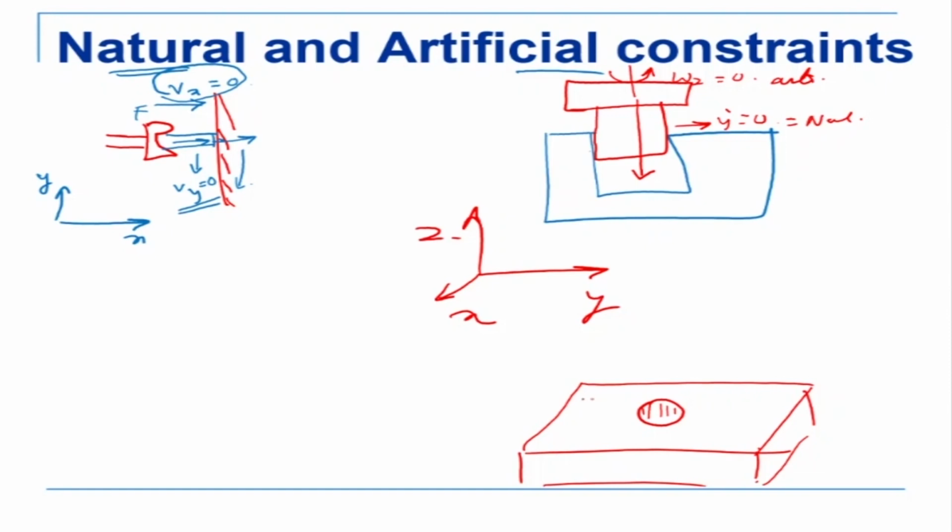So when the peg is here, if you can imagine that, let's say this is my peg, and I want to insert this into that hole. So the robot is holding this peg, and what it can do is it can try and approach the hole. So it has to have a velocity in that direction. Here it cannot force it down. So Fz must be equal to 0 because it can't force it through here. Sorry, Fz will not be 0, but the velocity in this direction, so Vz will be equal to 0, which is a natural constraint. So it cannot force the peg into this surface because there is no hole there. Only when it approaches the hole and reaches the hole, exactly fits the peg inside there, then it can have that velocity. Otherwise it cannot.